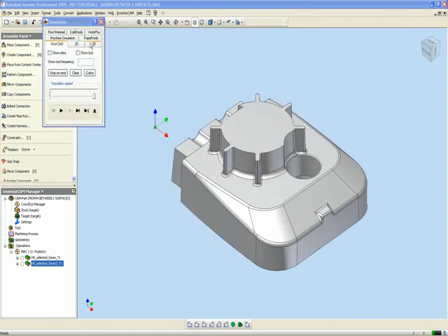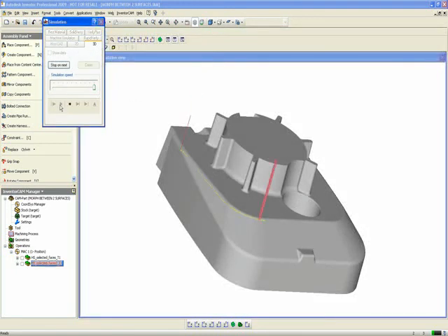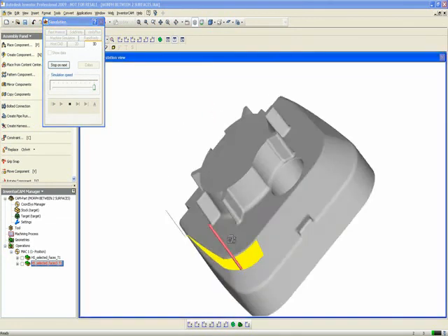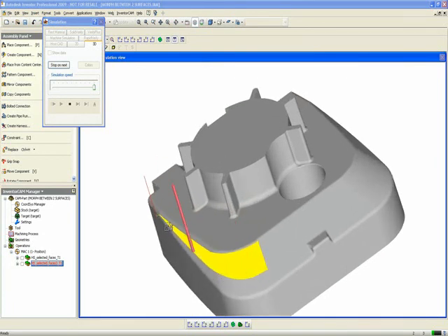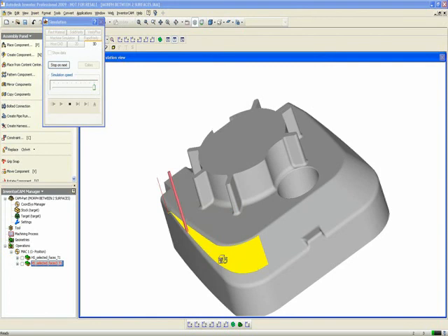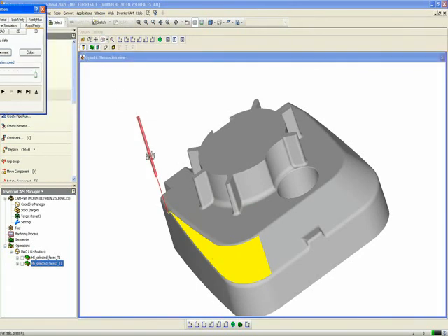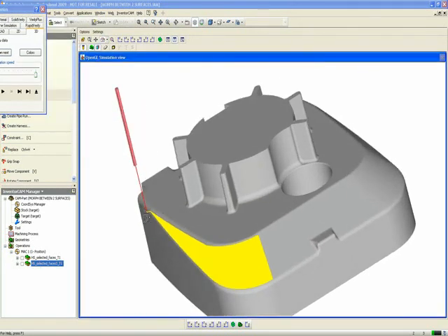And in my simulation, again, we'll use the 3D simulation. You'll note this time there are no jumping up of the tools to the clearance level. And at the end, you'll notice when it gets to the end, it'll also stay down without jumping up. And basically what we're having is one lead in, as you see over here. And now when the tool finishes, we'll also have one lead out, as shown over here.